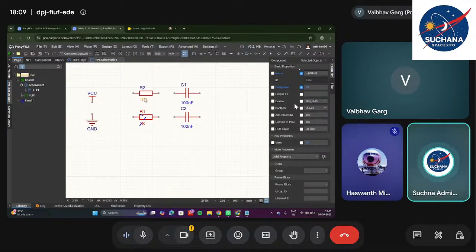Now I have already told you that the designator of a resistor should always begin with R. Is it a strict enforcement or is it just a nomenclature? Nomenclature. Now let's say instead of R1, you want to type res1. Res means resistor. So you can change the designator over there. But by default, it should be R. Now change it back to R, the standard one, R1.